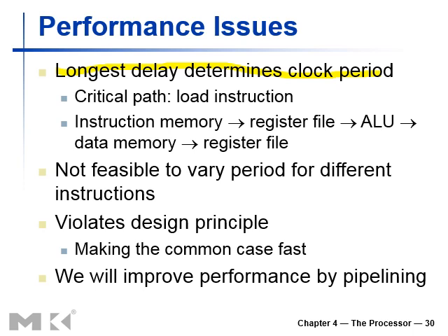So our critical path is basically the load instruction. That is the longest instruction, which consumes the fetch section, decode section, execution portion, data memory portion, and again back to the register file. So that is the longest. We can see that we've used instruction memory, then register file, then ALU, then data memory, and then again register file. So the delays of all the functional units will be added while determining the time for the load instruction.